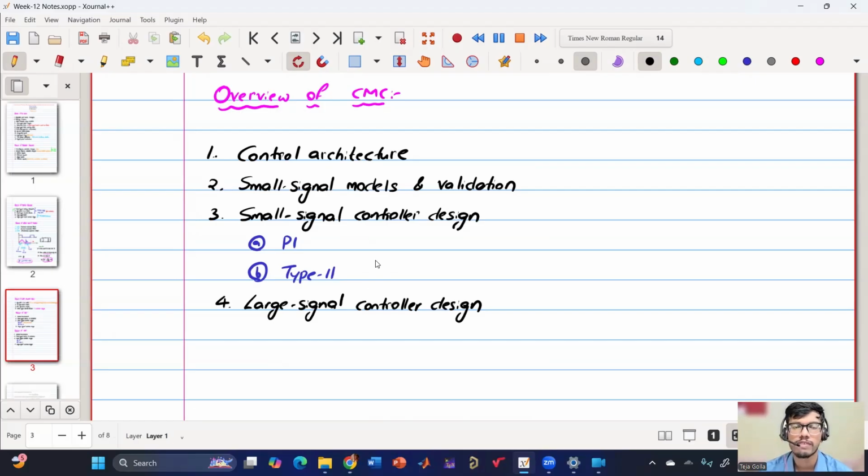And once it is going to the equilibrium point, how the switching will help us to go from one operating point to another operating point in one switching state. And in such cases, what will be the trajectory and what will be the mathematical expression. And then how to design the controller for that, how to get the PID gain so that it will reach the new operating point in one switching cycle. And then sir has shown the simulation and also the comparison between the large signal as well as the small signal tuning and how it can improve the performance.